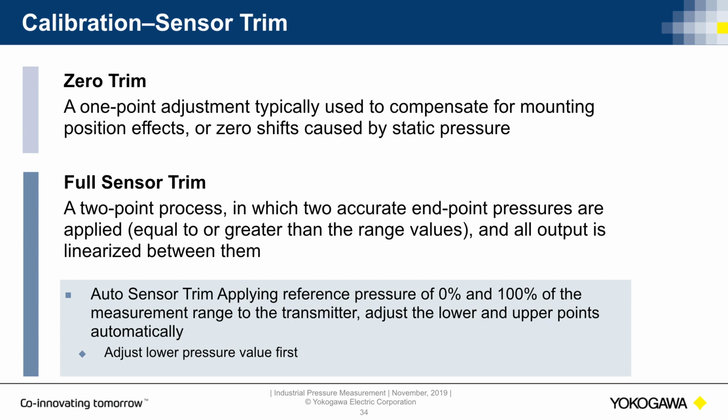And you always want to do that lower point first, just because if you do the upper point first, it's going to affect that lower point adjustment. So always do the 0 trim before you do a full scale trim.